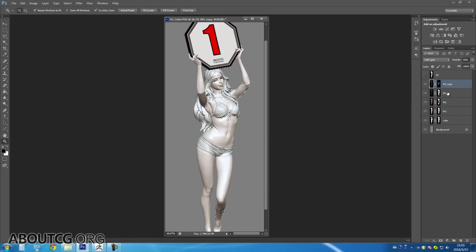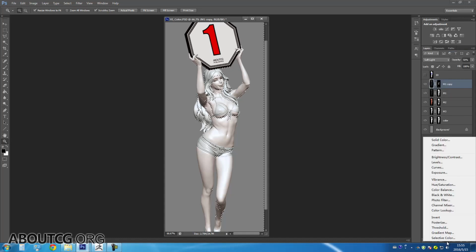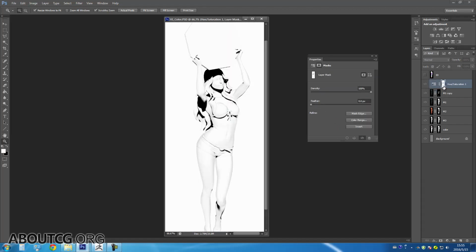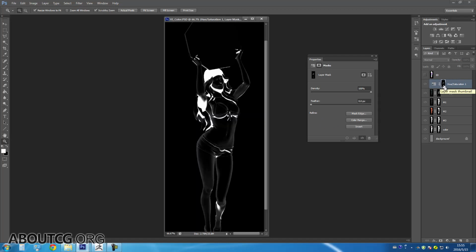If you need some color bias, you can adjust the color bias. Check the colorize option. We can use the display properties toggle to see the effect after adding the shadow and AO. After there are basically no issues, next we still need to do the final step, which is to bring in